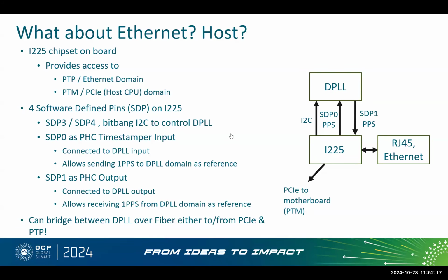Yeah. Exactly. So even just the time of day information, the DPLL is designed to do that fairly smoothly, but it also has some latency in access in terms of I2C, let's say. Let's say you're doing a lot of I2C to the DPLL to manage it for other reasons. You don't want to take up that time to just read the time of day when it got the 1 PPS. Yeah. You can do that also with the PTP, yeah. Or just Ethernet. And here too, you still have the same religious fervor on assuming that the two cables are the same length.